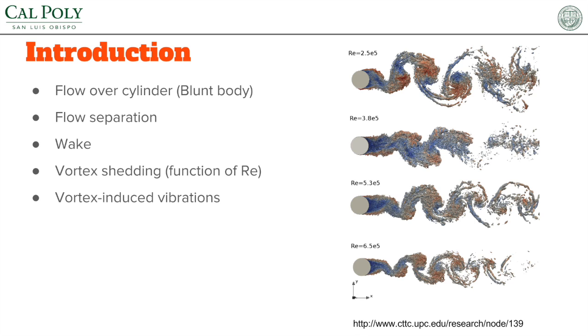External flow over a blunt body, such as a cylinder, will experience boundary layer separation, leading to wake flow oscillations. The viscosity of the fluid leads to the creation of a boundary layer. The boundary layer interacts with a change in pressure force exerted from the fluid. Some particles will reverse direction or completely stop, causing neighboring particles to separate from the cylinder.